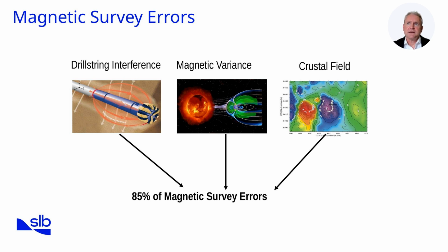Errors vary depending on well trajectory. When drilling east-west, the z-axis picks up more interference because it is perpendicular to Earth's field lines, leading to significant azimuth errors. By contrast, when drilling vertically, interference is minimized because the tool is aligned with Earth's field.